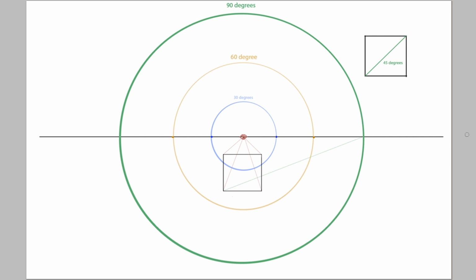One of the things we know about squares is that if we cut them in half, we're given a line at 45 degrees. So if we trace a line back from one of the close points to the 45-degree vanishing point, where it intersects with the line going back to the vanishing point is going to be our distance back for our cube. We can then use this intersecting point, expanding out and drawing lines for all of the remaining lines of the cube.